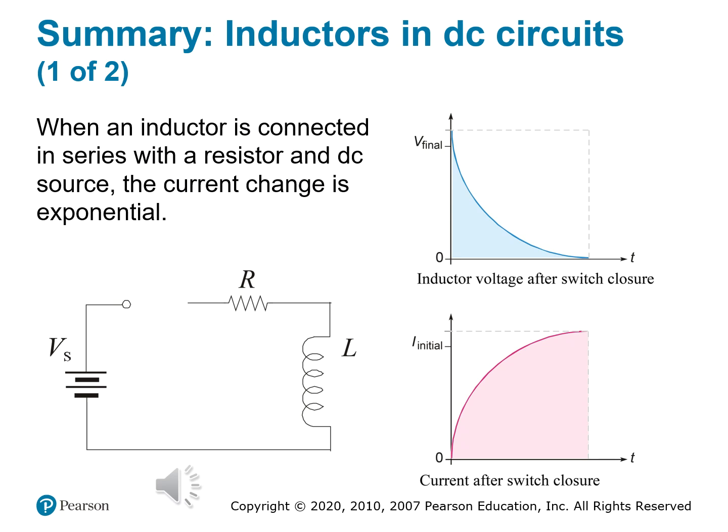So let's go ahead and summarize what we have here. Inductors don't stop DC. They just slow the rise of current when DC is first applied. And once the current stabilizes, the inductor behaves like a short circuit. And the principle in this essentially is that it provides surge limiting, it helps in switching converters, and helps with power up sequencing, like in digital systems.